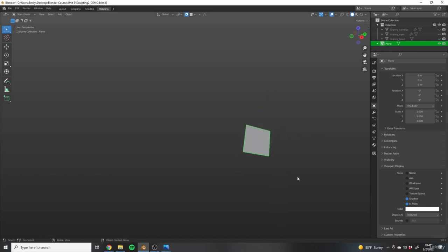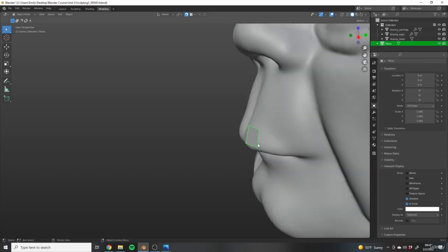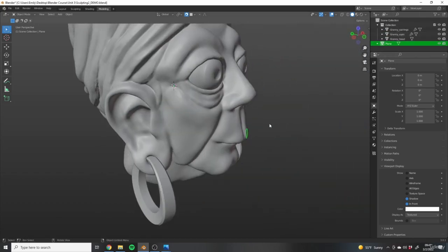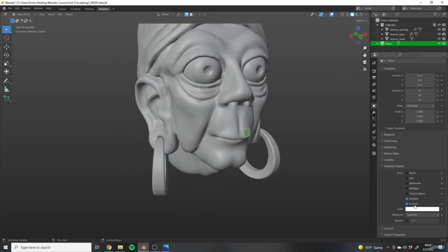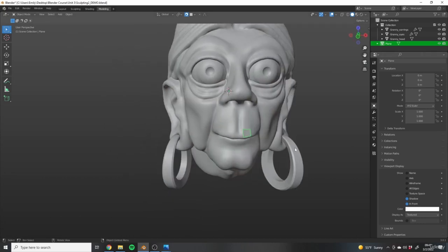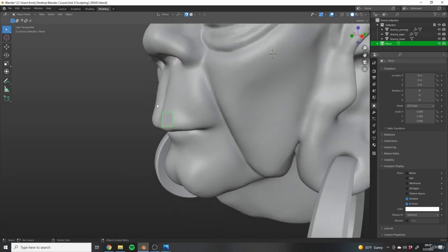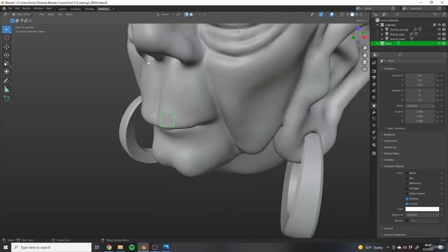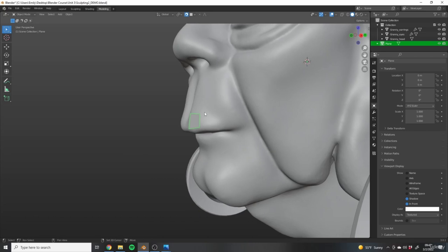Normally this is not an issue, but you will notice that as we start to pull things around to the back of this, because we have this rendering in front, it's going to get very confusing as to what we're looking at, whether we are looking at the front of a face or the back of something in the back. So we need to turn on backface culling.